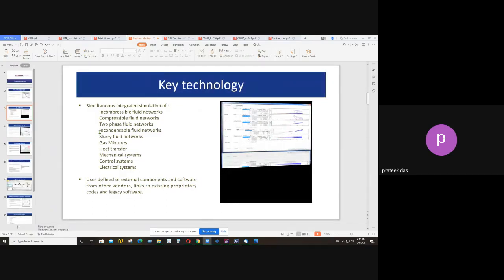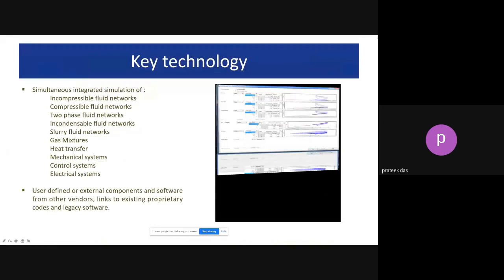It is very handy when you are going to simulate a larger network in automated mode, or if you want to give any feedback, like pressure or temperature feedback, in order to achieve stability inside the system, then you can utilize these digital control system libraries. It has proportional, integral, and derivative controllers. By utilizing these, you can add automation to the models.